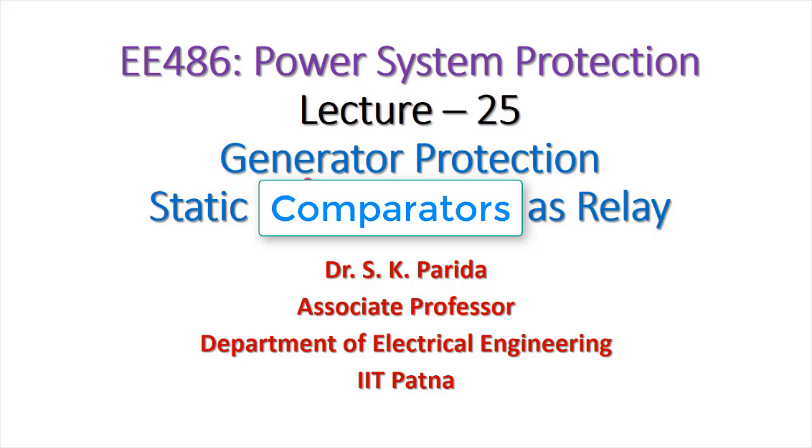It is named in a different way, longitudinal protection, in case of generator protection, though it's a simple percentage differential relay, because we are using another kind of differential relay which is known as transverse differential relay, which is used to detect the interturn faults in the stator winding. And therefore these two terms are used. One is your longitudinal differential relay, which is a normal percentage differential relay, and another one is your transverse differential relay, which is used to detect the interturn faults in the stator winding.